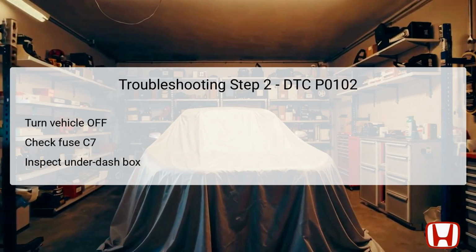In the second troubleshooting step, the technician needs to turn the vehicle to the off or lock mode. Following this, the next critical action is to check the status of fuse number C7, which is a 15-amp fuse located in the under-fuse/relay box. This fuse is vital for the functionality of the MAF sensor circuit. If the fuse appears blown, it will need to be replaced.